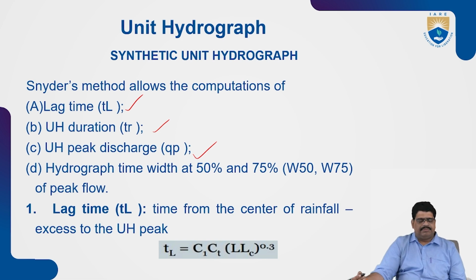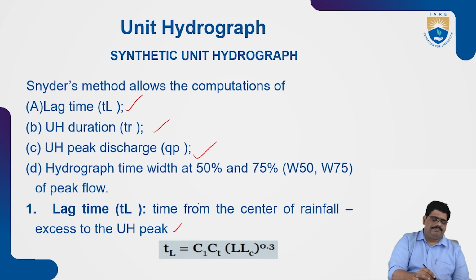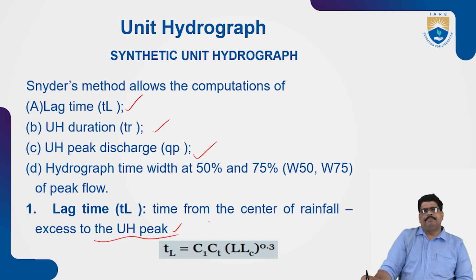What is meant by lag time? Lag time is the time from the center of the rainfall excess to the peak of the unit hydrograph. So we call that the lag time. This definition is very important. So how can we calculate the lag time?